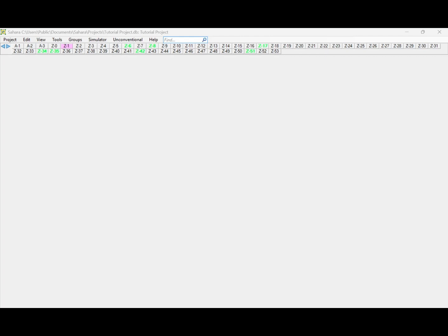So you are going to iterate and do a first approach: initialize these coefficients, then calculate your total liquid rate and your oil rate, see if it makes sense with the method and the coefficients that you define, and then adjust the coefficients over and over until you have a good match with the history data.